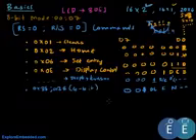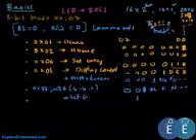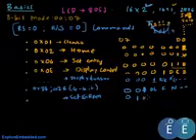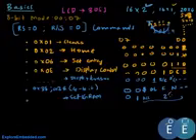Okay, now the next command, as you could guess, the one shifts here, and this is called the set CGRAM address. Now CGRAM, by the way, is used to store custom characters, and there are 6 bits that are remaining here. So 2 to the power 6 is 64.